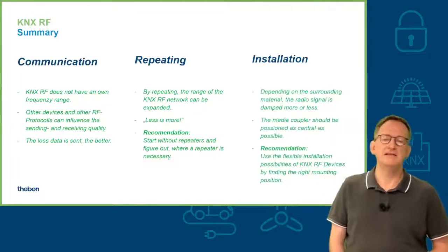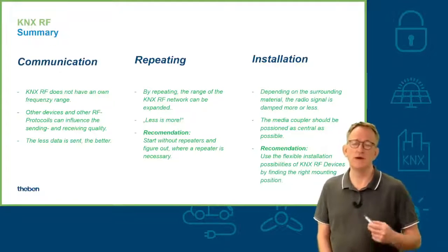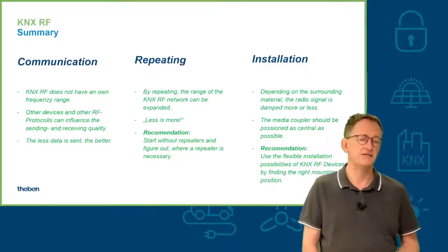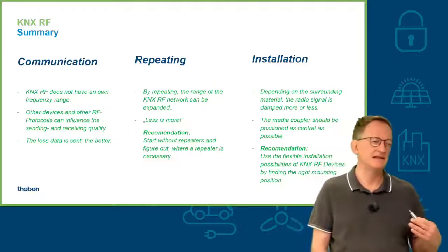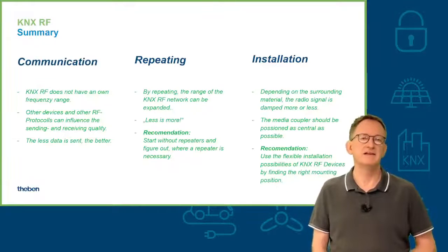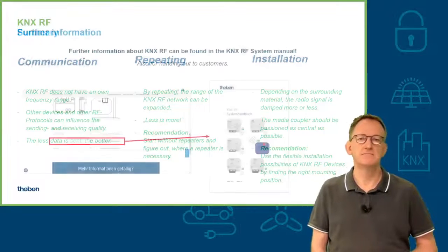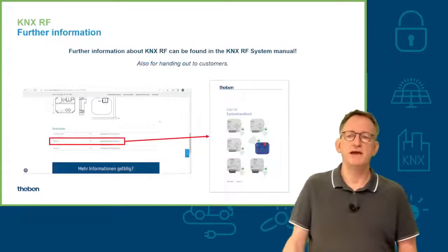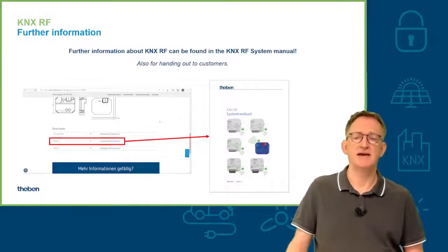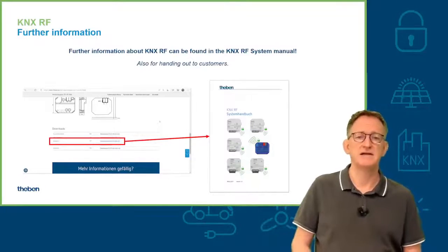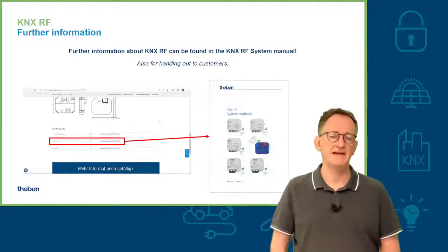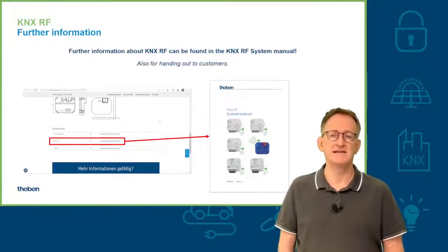And for installation, you should really think about where you install your media coupler, your RF devices and so on, so that they are installed in positions where the damping is not that high. We also have additional documentation and handbooks about the RF situation. That's our RF system handbook. You can download it from our webpage, and there you find a few more hints, also described in detail.